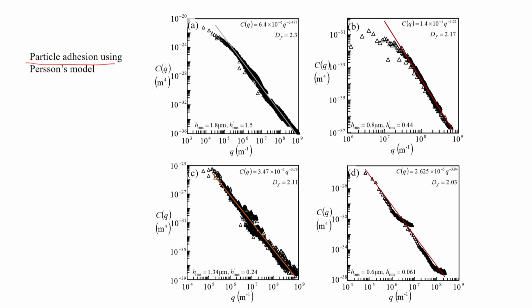So, how exactly do we do that? The surfaces that we have are different. We can design different surfaces having different fractal dimensions, and we can estimate the surface roughness by this RMS roughness, considering the whole range of surface features, from very small to large. For all these cases, this HRMS is characterized over the whole range, and we have these PSD curves.